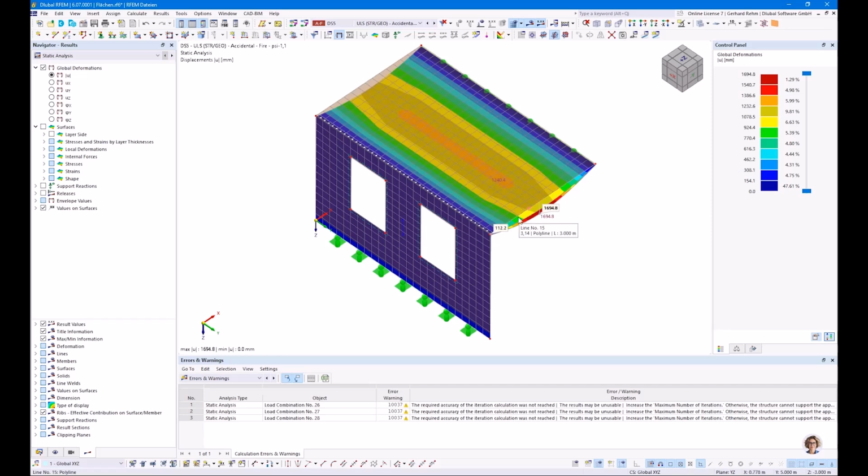Of course, it's clear nobody would apply 90 minutes to an 80 millimeter panel. So it can happen that the structure becomes unstable, especially when we talk about P-delta analysis, so second order effects. Then of course the critical load factor plays an important role, and the structure becomes unstable under some circumstances. This needs to be considered. Okay, so in this case, it's clear this floor will definitely not work.